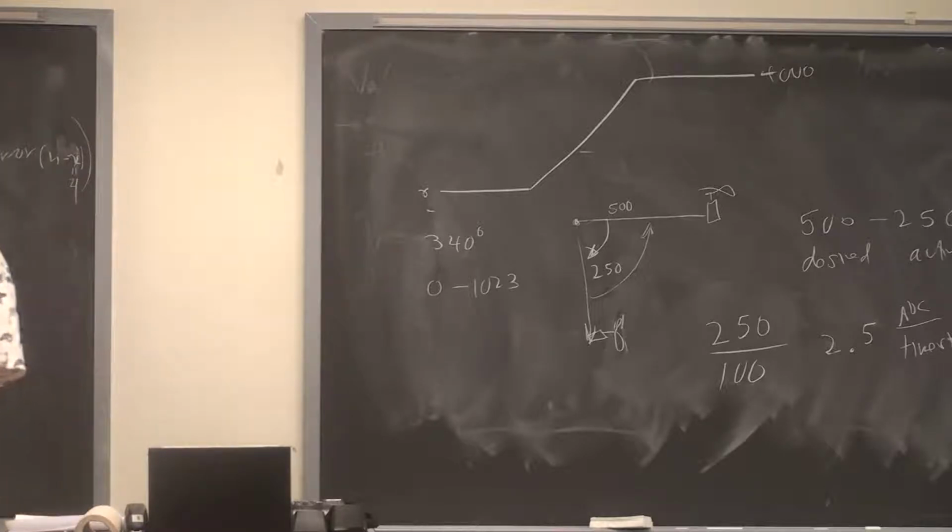The resolution is as good as you're going to get because that's the measurement you can make, right? So why not do that? Don't convert it to volts, don't convert it to radians, just use the output of the ADC 0 through 1023. How do you want us to calculate the angles we're setting, like 30 degrees?